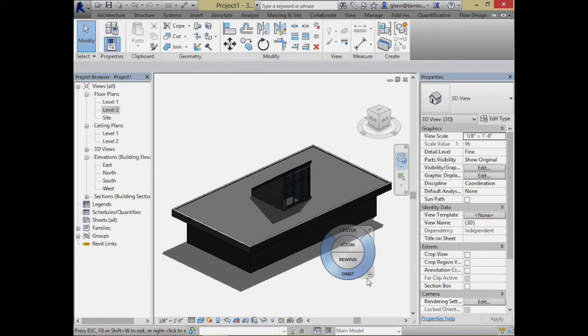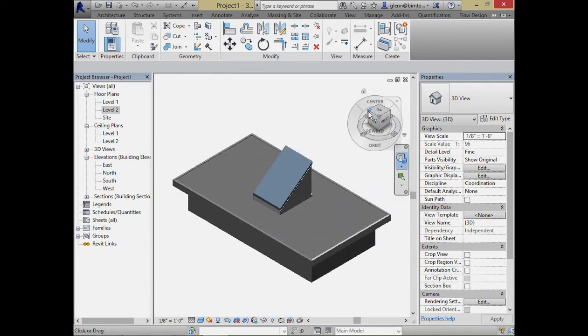Okay, does daylight come from the north side? Yep. So daylight comes from every side of the building uniformly. So in terms of getting daylight in there, the north side is pretty good. Does sunlight come in from the north side? At least not in the northern hemisphere. Okay, so for a lot of spaces like artist studios and things like that, they actually put all these skylights facing the north, because they want the nice daylight, but they don't want the direct sunlight on your painting or bothering you as you're trying to work in that studio space. So it creates sort of a nice ambiance for you there.